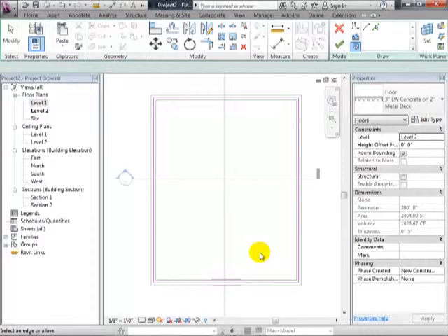Sorry. Oh, no worries. What you do is you choose the floor, and then we'll say edit its boundary. Right up in there. Then we'll go back to the floor plan level. So looking at that's good. And then we'll see its boundary. And now we can go ahead and choose its span direction, right here.